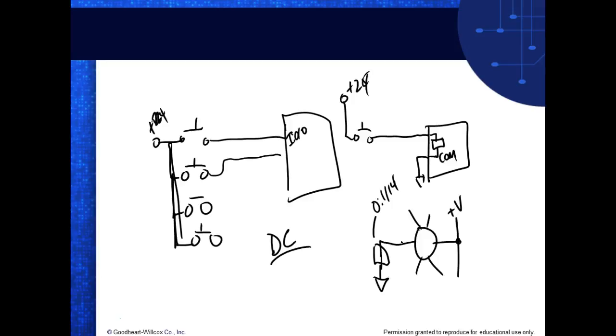Common is just, we've got to have two wires. So over here, these push buttons are using a positive common. Right? And what's that positive voltage looking for? Well, it's looking for a negative common, right? You understand that? So a sourcing input device would have to go to a sinking input. Y'all understand that? Sourcing is a positive common, and sinking is the negative common.